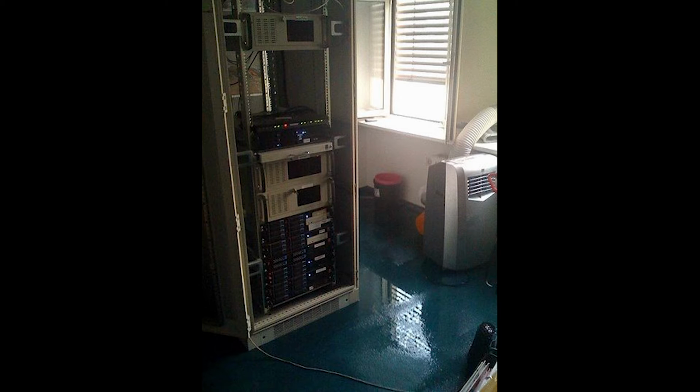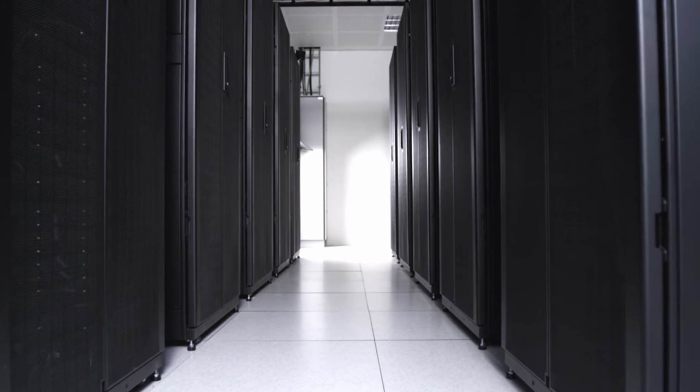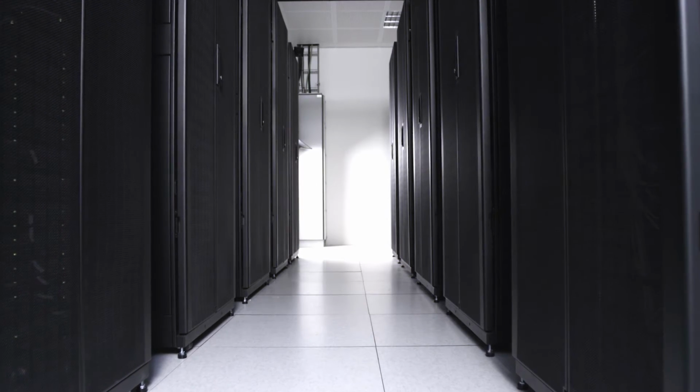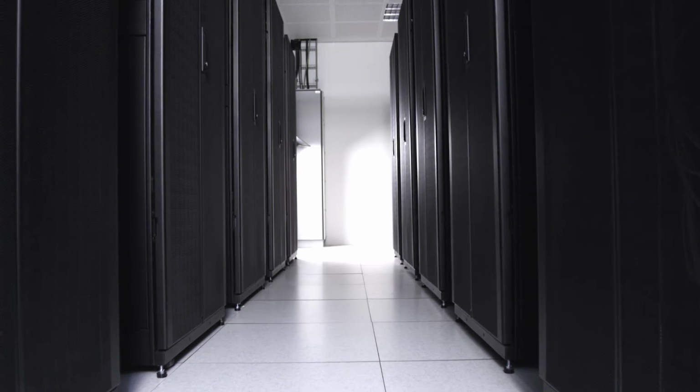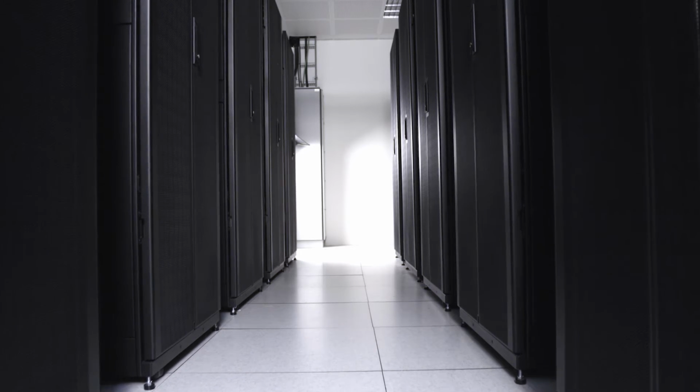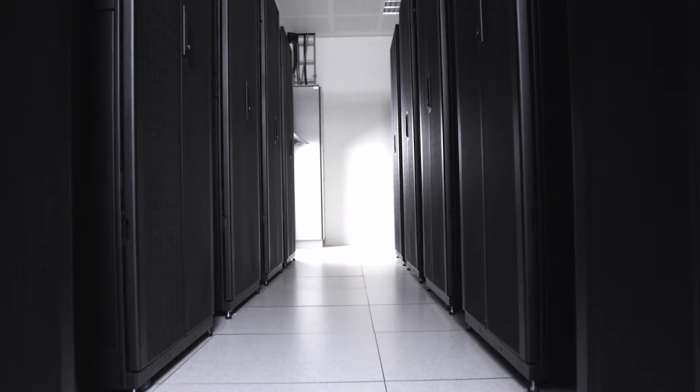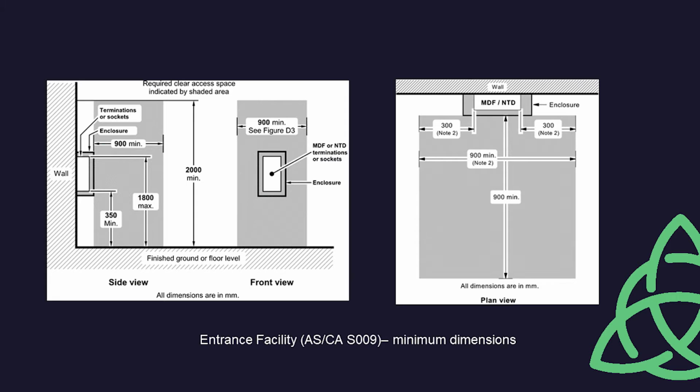It is preferred practice to locate a telecommunications room on every floor. We have come across many situations where this space has serviced multiple floors, typically one floor above and one floor below. For the design and construction of the building, it seems like a win-win solution to save cost and space. When it comes to operating the facility and doing moves, adds or changes, it can quickly become a hard, poorly documented, expensive outcome. Therefore, it is also preferred for the telecommunications room to be located as close as practicable to the center, core area of the area that will be served. Telecommunications room requirements are discussed in greater detail in Section 3 of AS NZS 3084.